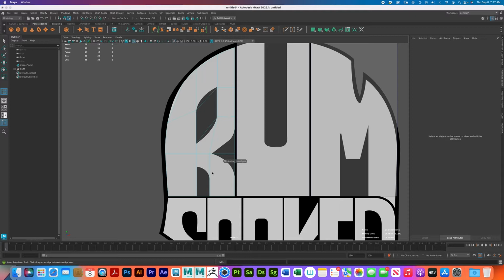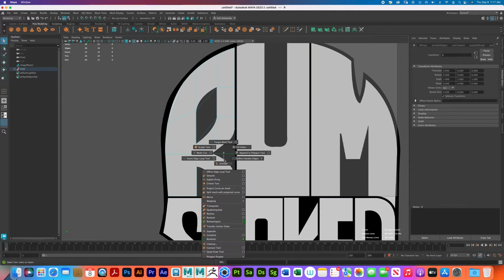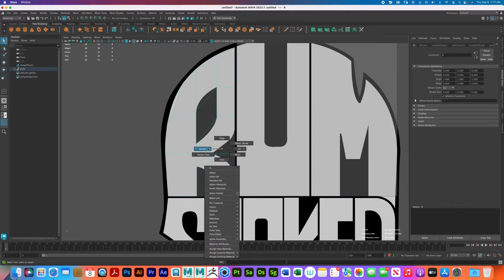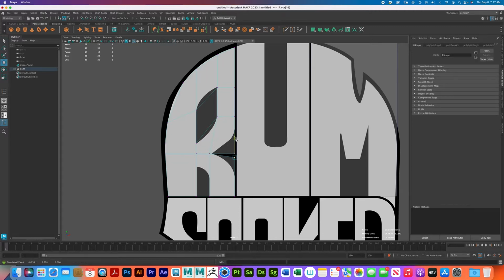Anyway, what I was gonna say was, if you click one edge, shift right click, and you're gonna add detach. Object mode. And if I right click and do the vertex and press W, I don't have to go crazy. I'll just push that down to about there. I'm gonna push this one up here, and I think that's good for me right there.